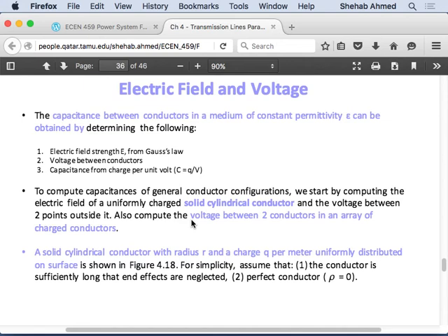Fine tune what I said on a stranded conductor. Everything we're doing was more a solid conductor. I was considering the radius. Okay, if it's not a solid conductor and it's stranded, it's not radius anymore, you have to use a geometric mean radius. How about if it's not a stranded conductor, it's a bundled conductor? So this phase is made of 4 bundles. The radius will change, and there's a way to calculate the corresponding radius, but there will be a radius that you would use in the same equation that I have, right?